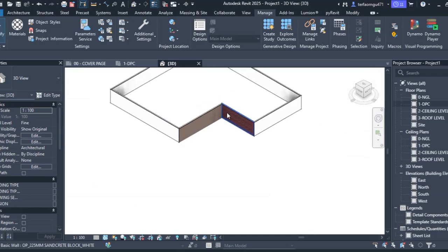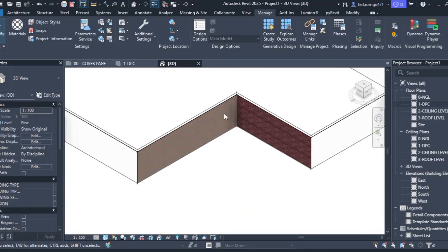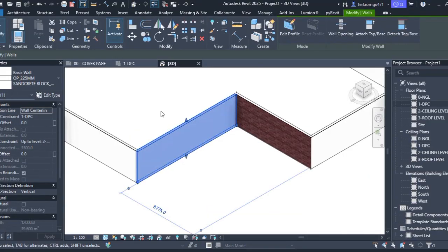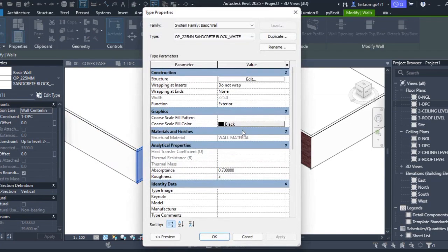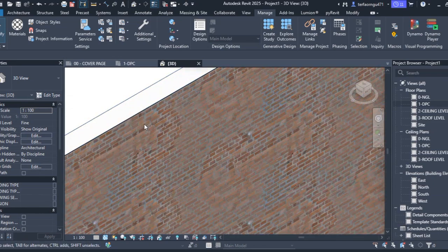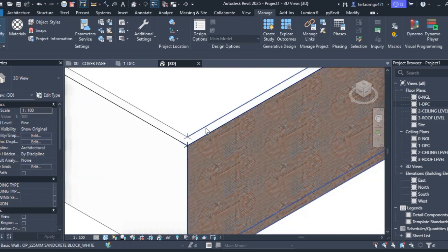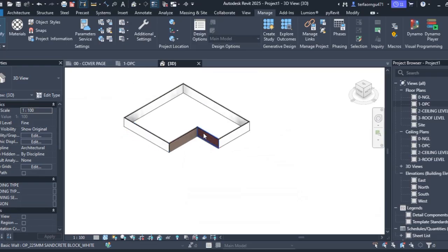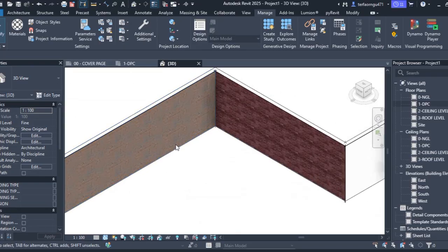So now we have created a new material. So you'll notice this particular wall here still has the same material, which is the wall material we created earlier, but the surface, that's this front surface that we painted, now has a different material, but the rest of the wall still maintains the same material. So this can help you to have variations in your paints and still maintain the same material, instead of going to assign a material to each particular wall, which can be very tedious and might take you a whole lot of time.